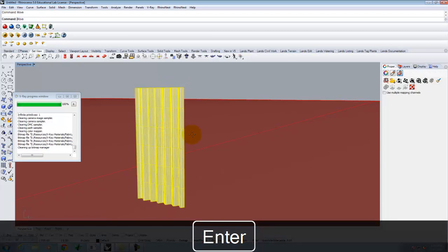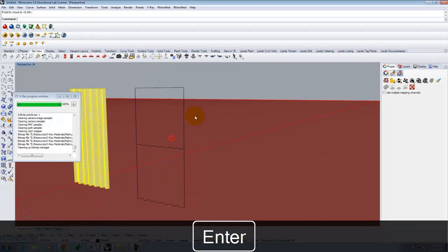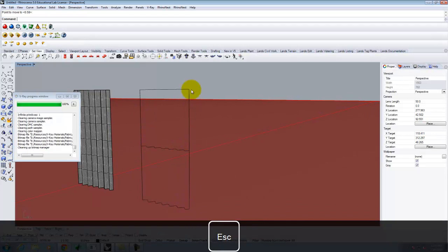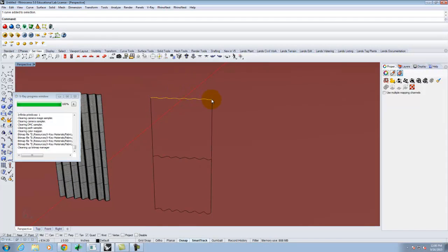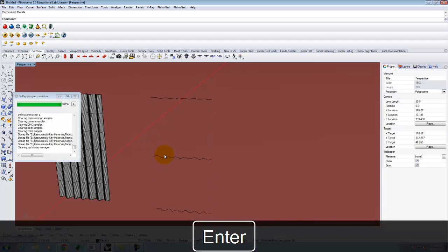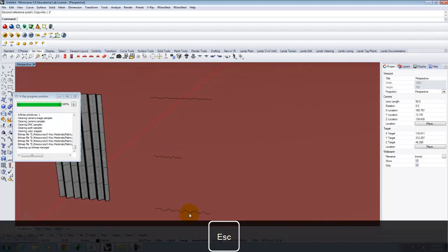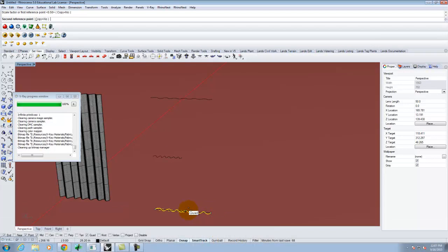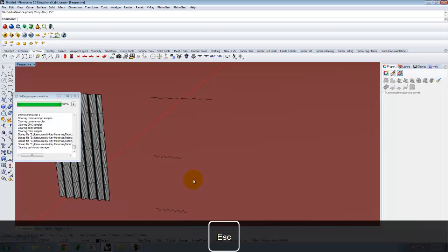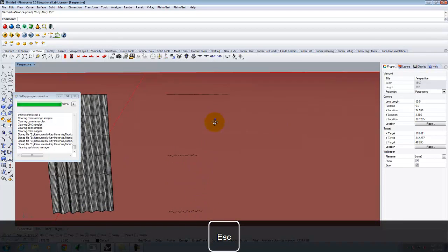If I want to make this a little bit more complex, let's start adjusting things. Let's say that the top is going to be the largest point, and then I want to sway the curtain back so that the center is tied back a little bit. Let's take this point here. I'm going to delete these side curves for now. Let's do a scale 1D of this, and pull this back to maybe 2 feet. Let's scale 1D of this, and maybe this is 2'4", something like that, because it's going to bunch and fall out a little bit.